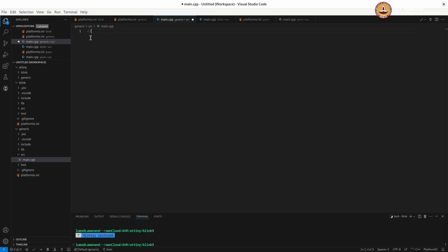So let me first define the CPU clock frequency, and I will say that if not defined F_CPU, I shall define F_CPU as 8 megahertz.